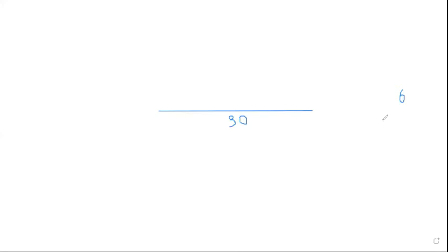Now, if we tell you to divide it into 7 equal parts, is it possible by scale? No, sir, it is in decimals, sir. This is not on your scale. So how can you divide it? This is 30 millimeter. So what will you do? At this point, you draw a line at less than 90 degrees.